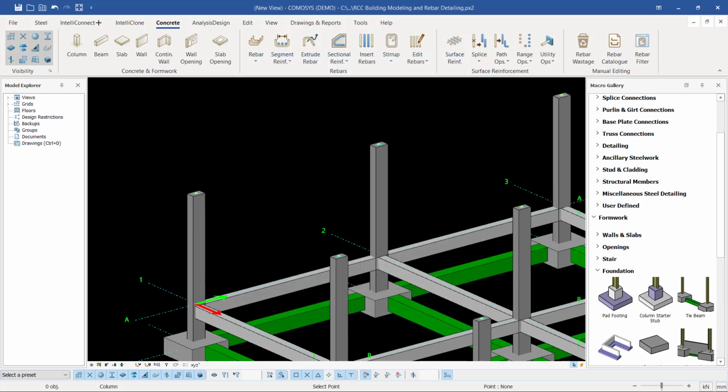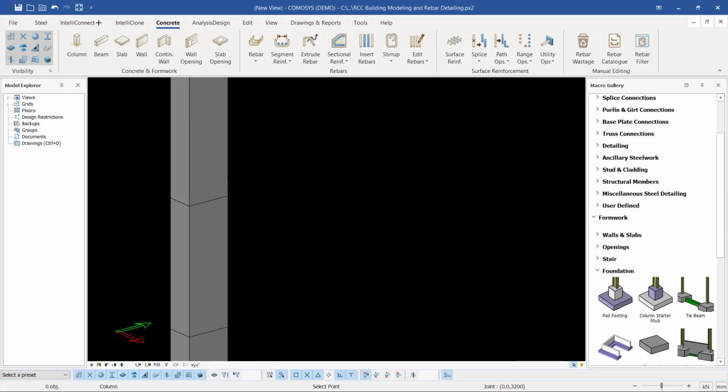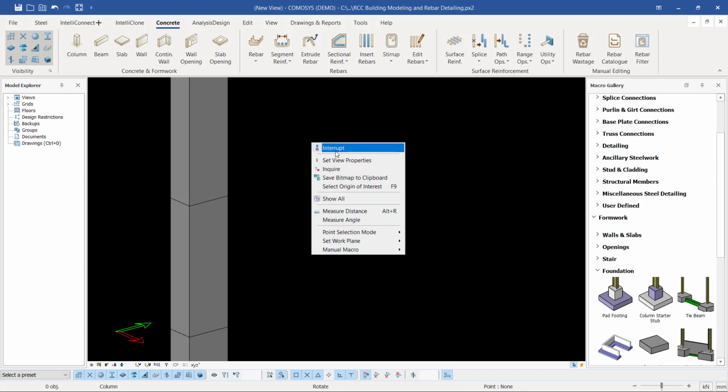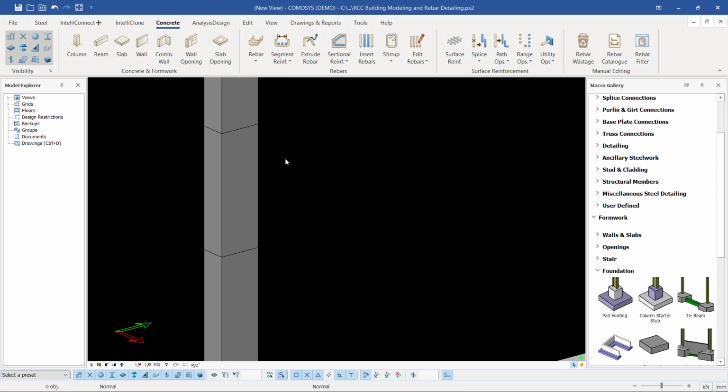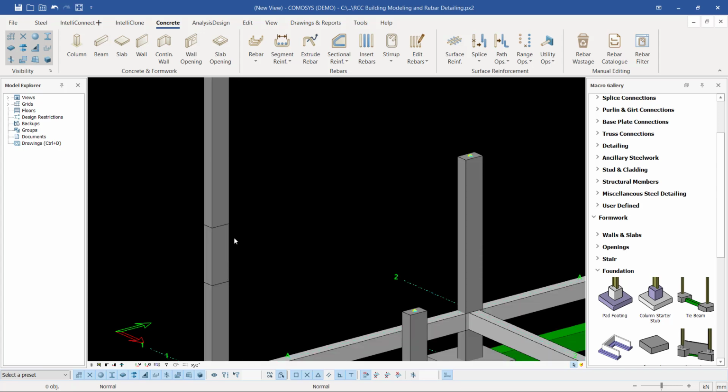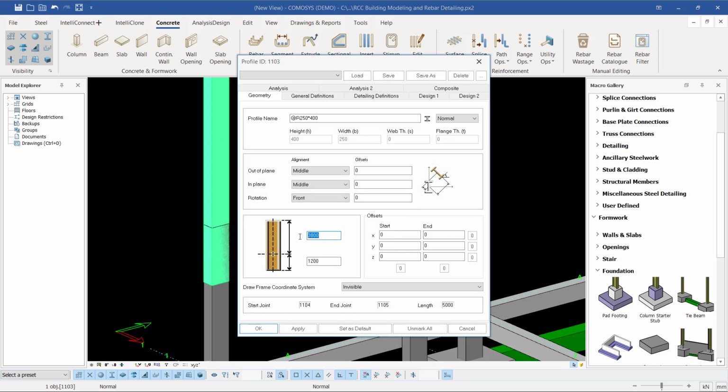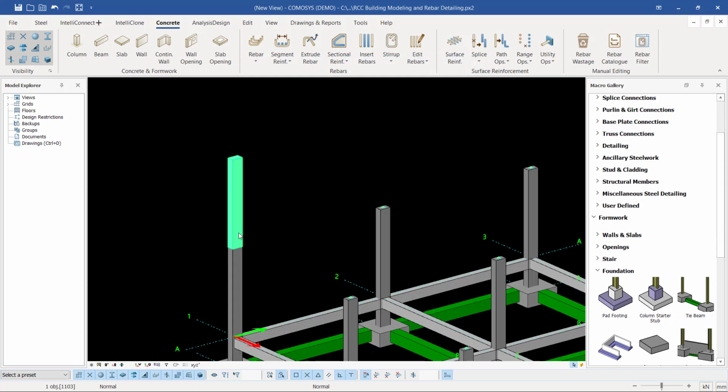I'm going to go straight to my column and snap right here. My column is right here, and you can see it has overlapped this by 1.2. I want to adjust that, so I'm going to double click on it and change this to 3.2 and click OK, and remove that, make it 0, click apply and give it an OK. So we have this in place.